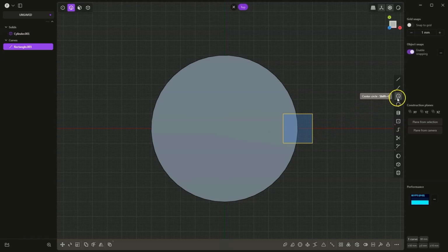Next, I select to draw a circle, but this time I choose to draw a circle from 2 points. To activate the circle drawing command selection menu, we hover the cursor here, click the left mouse button, and select the command we want to use. Now we draw the circle by specifying 2 points on the circle. We will use snaps here. When the snap on this point is active, we click the left mouse button. Then we specify the second point and click the left mouse button again.